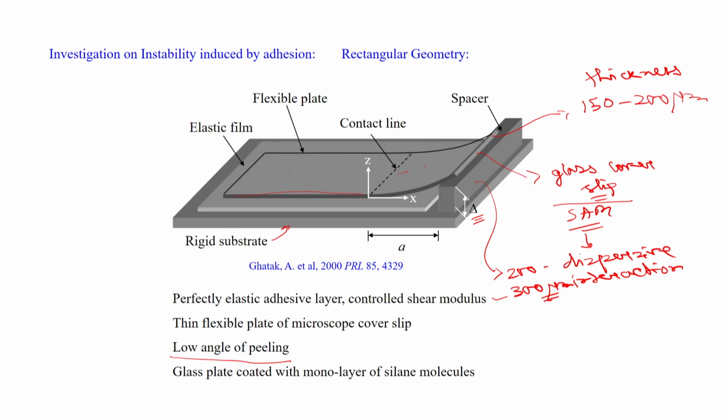this flexible plate is somewhat stiffer in comparison with most adhesive tapes. Okay. So, we have done it by design to satisfy the condition of very small bending approximations. So, we want to do the experiments at a very small bending approximation. That is why we have kept this peel angle. If you measure the peel angle, it will come out to be a degree or so. Theta will be 1 to 2 degrees, not more than that.